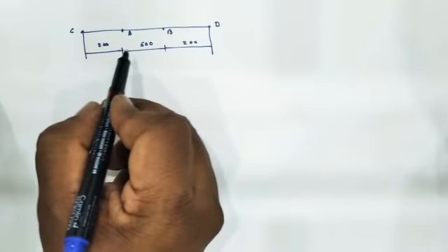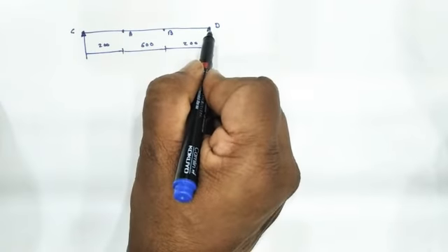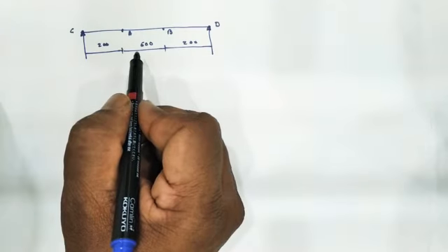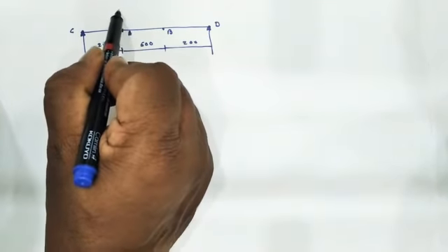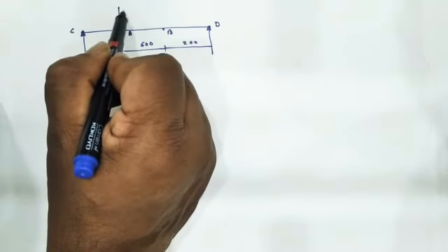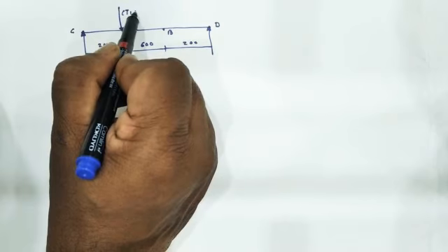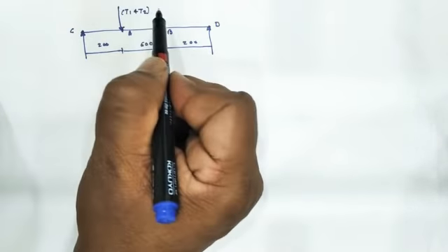Now we'll see the vertical loading diagram. Again the same free body diagram. As from the first figure, pulley A transmits the power in a vertical direction. So at location A, the sum of T1 and T2 is a net vertical downward force.